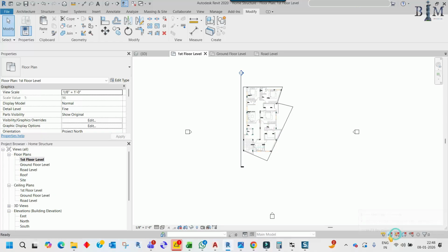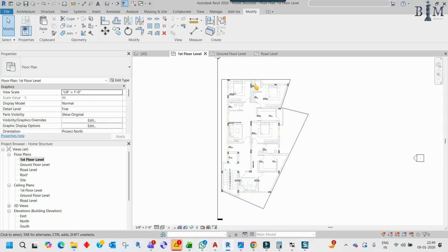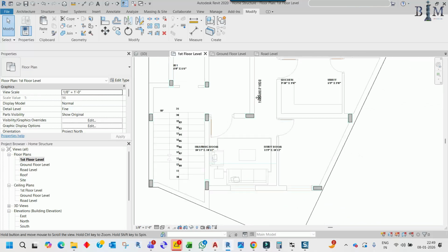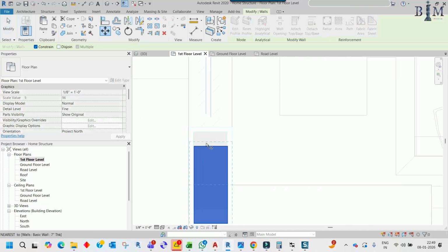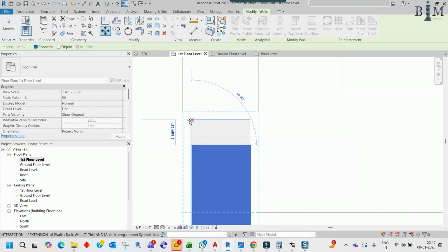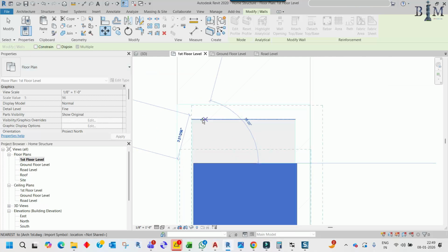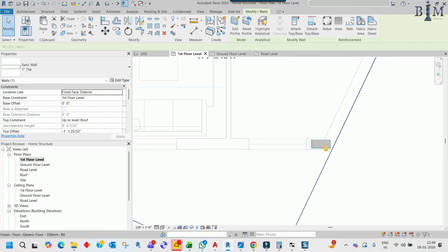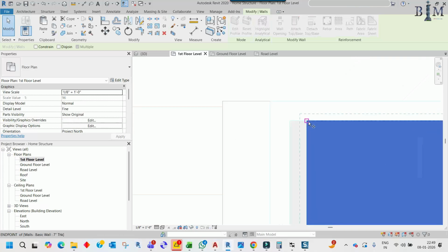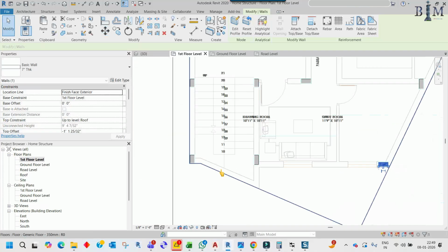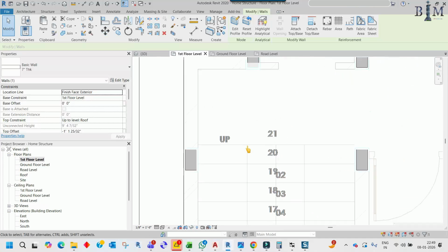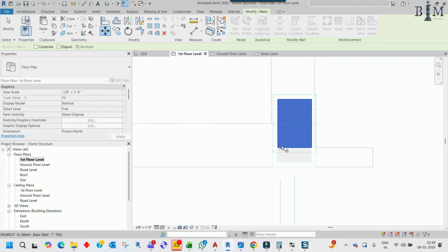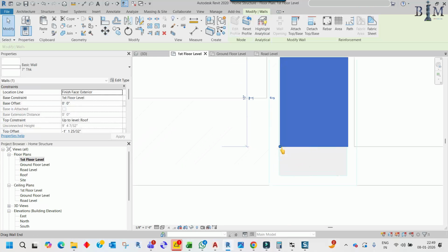Okay, and here the Pin and Attachment option I have to take. So here you can see all the columns, and it is matching, but sometimes you can see this column is not matching. In that case, just take this point, okay, so remove constraint and take this point here, and now it is moving. So again let me check another column, it is also not matching, so move it here, and let me find the other columns, it is matching, it is matching, it is matching, and it is not matching. So here let me check the sizes, so it is not matching because the size is different.